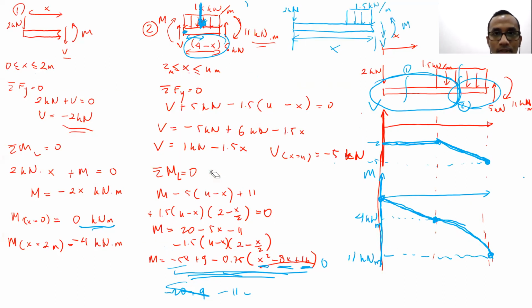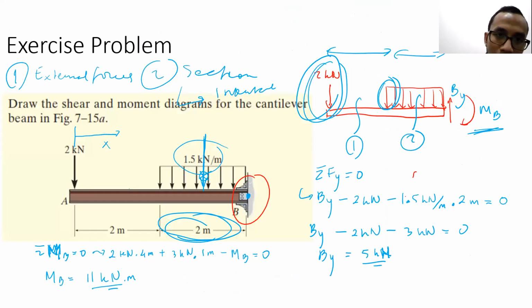from the final calculation of the distributed force, you cannot just think about the distributed force as a concentrated load at 3 meters from the left edge, because the distribution will not be correct later, or 1 meter from the right edge. So the distribution will not be correct there. So whenever we have a free body diagram, okay, we can do the representative concentrated load of a distributed load. We can do that, but it's for each free body diagram.